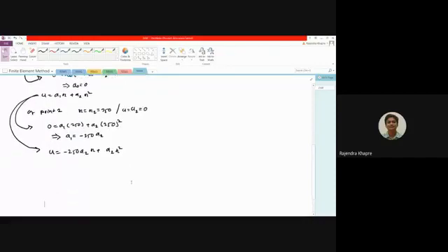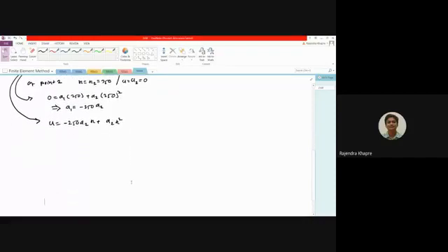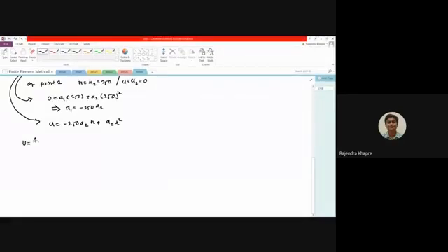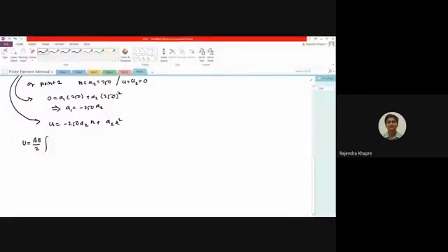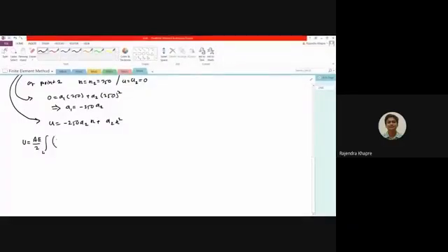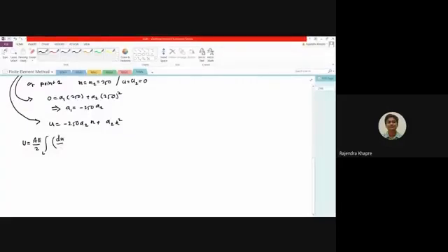So now ultimately we are interested in finding out the strain energy. Now in case of a bar element, so I'm talking about bars over here, your strain energy U can be calculated as a simple expression AE divided by 2, integration over the length, into du by dx whole square into dx.